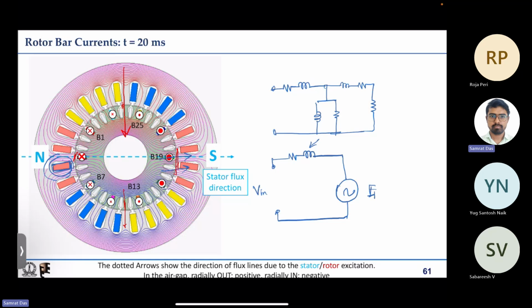Also, it is not necessary that you always go to the steady state equivalent circuit and apply the power balance theorem, and then indicate the power transfer by some dissipative element in the form of a resistance, where the current squared multiplied by this resistance is the electromechanical power transfer.